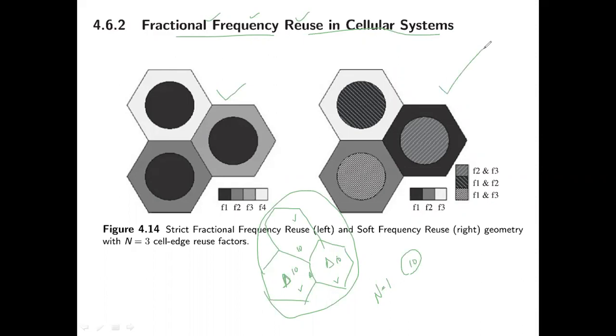In the first approach, you can see, suppose I have 4 sets of frequencies at my disposal. Now you can see, the same set of frequencies, whatever you are going to use, you are using only in the inner radius where the tower is situated. If there is a user here, he will not be allocated the same frequencies which might be there in the adjacent cell. Suppose this particular user is here. You can see now your minimum distance is being maintained.